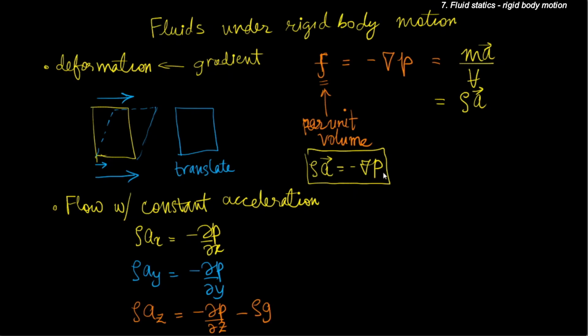So here I have explicitly not written gravity, but in general the force acting on a fluid element is due to the pressure gradient and the action of its body weight, that is gravity. So plus rho g, but when we substitute that g is equal to minus g acting in the e_z direction, we obtain this particular relationship. So these are the three equations which govern.